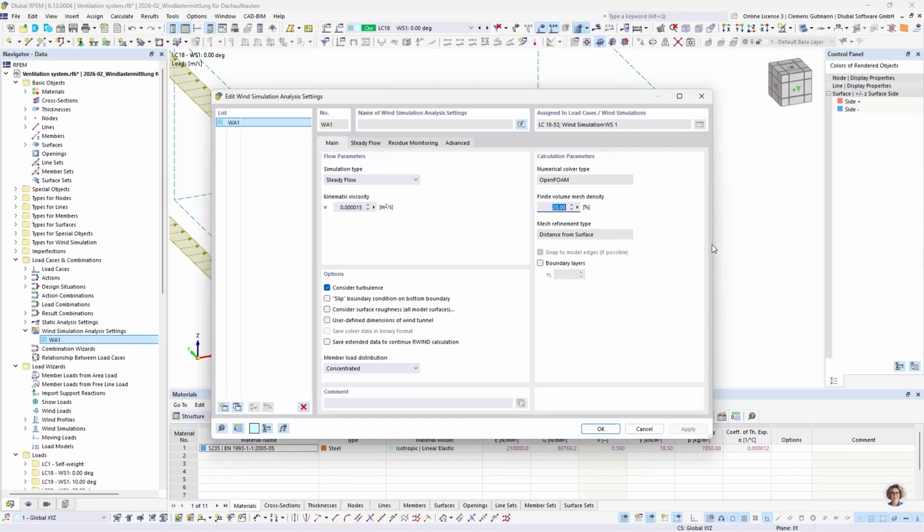Please note that this factor, or this algorithm, doesn't behave in a linear way. So if you want to carry out a mesh independency study, this can hardly be done by using this algorithm. Here it is better to use manual mesh refinements, because it's an algorithm that doesn't refine the mesh linearly, and hence it is not suitable for a mesh independency study.